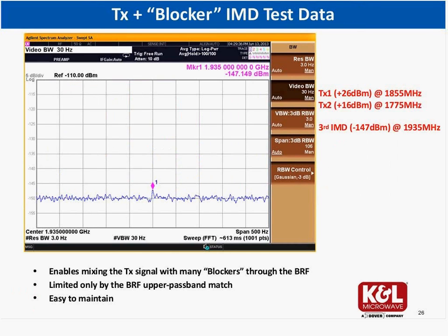And these are measurements that we took to make sure we can guarantee minus 140 dBm for plus 26 TX1, plus 16 TX2. I believe that we can push that even further down to minus 145 in a short time, just by incorporating everything that we learned from the high power solutions.